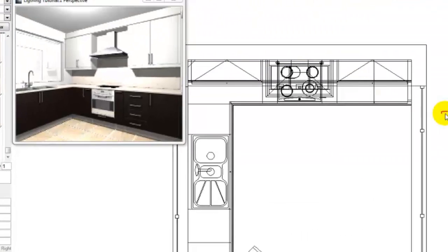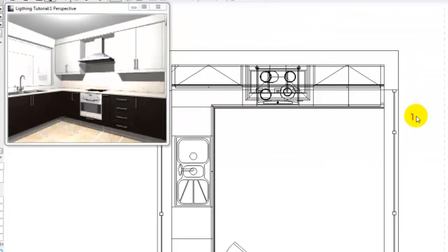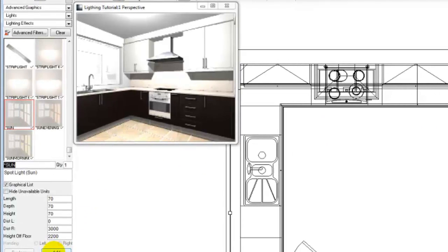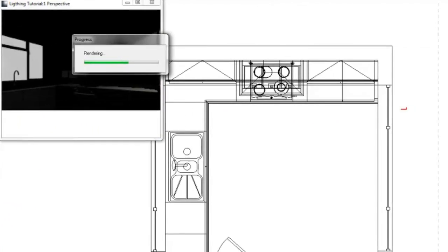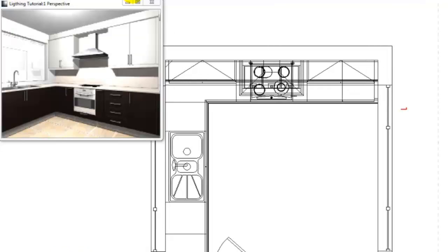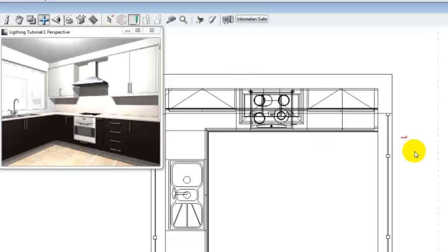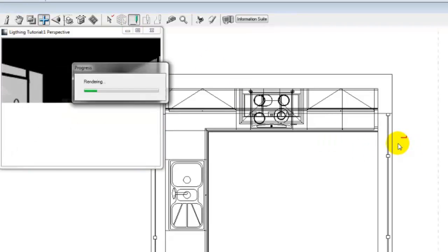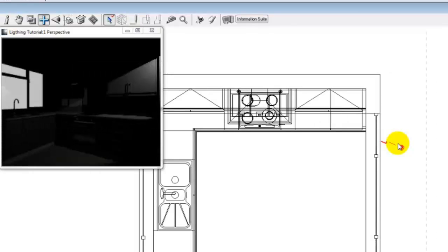To place the sun in the design, place the cursor where the light should appear. Locate the required light in the unit section of the Add palette. Press Enter or click the Add button. You can also use your single place item tool to drag in the exact direction you wish the angle of the light to be, similar to the star spot item. The light will be added in the design at the cursor position. This concludes part 1 of this tutorial.